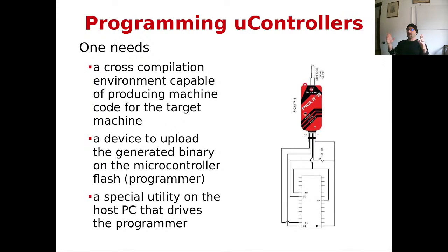In order to program a microcontroller, assuming that you have your binary blob, so you wrote the program in machine language and you have it in a file on your PC, the typical pattern was that you connected the programmer to your computer, connected the programmer to the microcontroller by specific lines, and then you ran a program on your computer that was talking with the programming device, and this program uploaded through the programmer the data on the flash, the non-volatile memory that is inside the microcontroller. Then once you disconnect the programmer, the microcontroller starts executing the newly installed program.